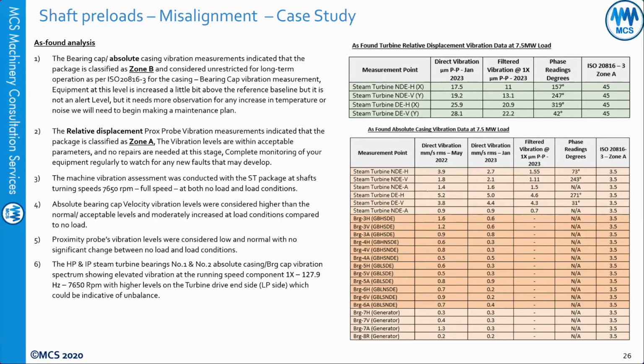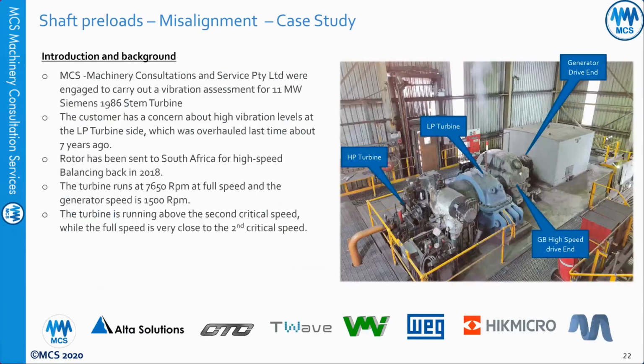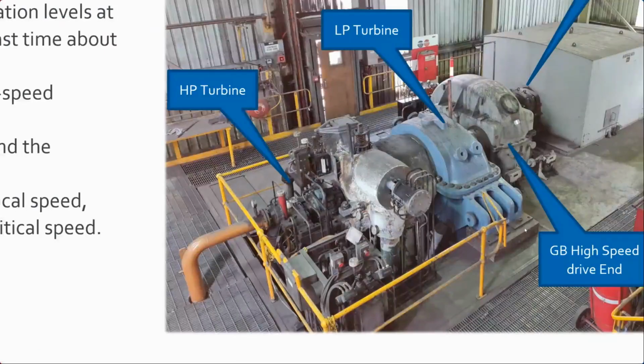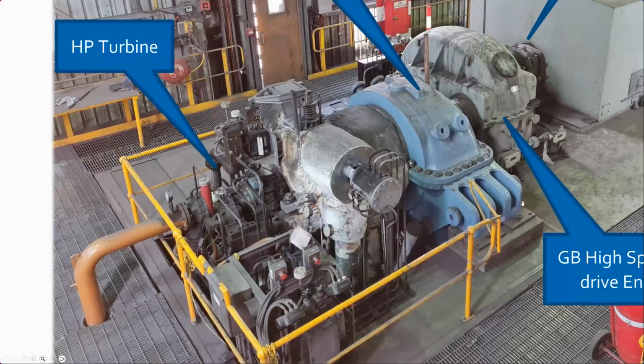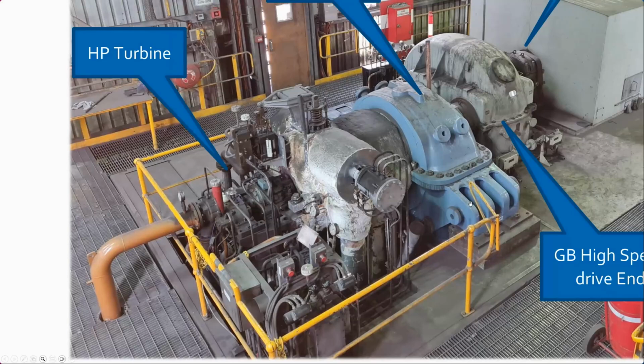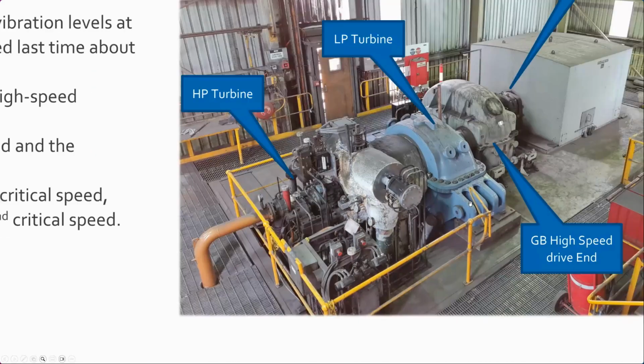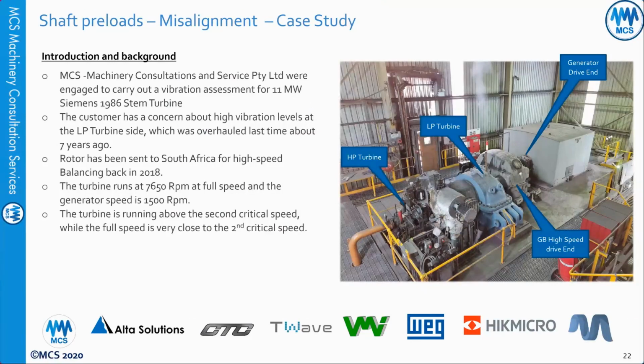There are many factors. If you look at the turbine design itself, there are these bolts here, and this is a bit of an old photo. There were jack bolts on the sides, and these jack bolts were very tightened, and when the turbine gets hot, it needs to move a little bit. These jack bolts weren't enabled. This photo was taken before they added the jack bolts here, which were used to do the alignment, and this was also another problem: these jack bolts affect the thermal expansion of the turbine,